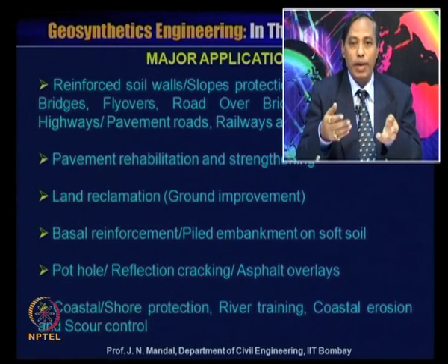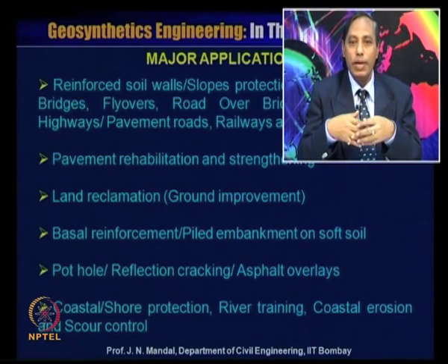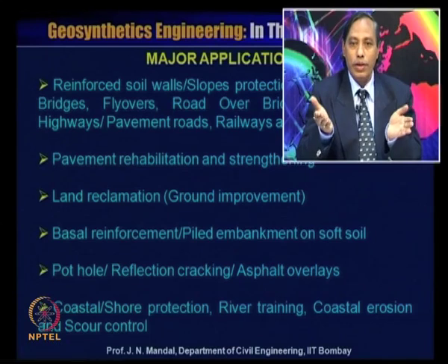If you go for the piling system, it will be very expensive and it will take a lot of time. So, if you place a layer of basal reinforcement on top of the pile, then you can reduce the diameter of the pile, and the spacing can also be increased. So, you can save a lot of money, and the geosynthetic material provides very good tensile strength.